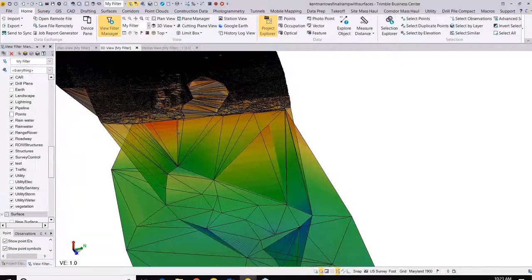If you're on the water for more than 4 hours that day, you're going to mark the notes on that tide. Depending on what area you're in, usually you want to start off at a tide gauge, and then hit the DNR benchmark. Usually in the area they have 4 DNR nails set up at whatever they call their 0 mark.